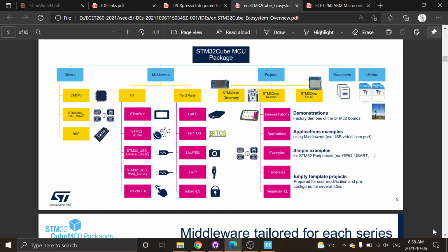One of the reasons I did it, had you do it, was because it also gives us a graphical indication of all the pins I probably shouldn't touch, because there's other things on the board that might interfere with things. And so we did that. Now, HAL often calls into CMSIS, which is a little lower. All of these are different layers of abstraction.